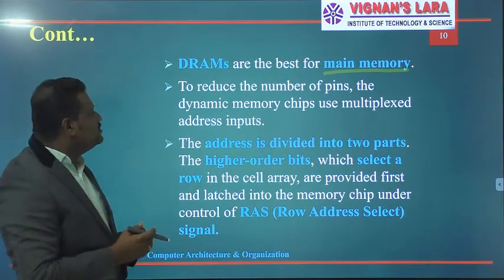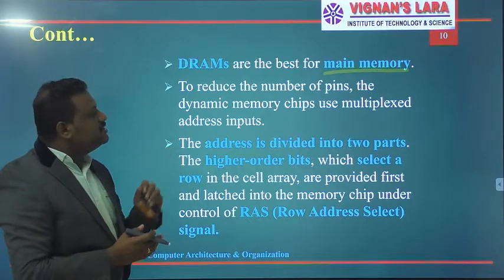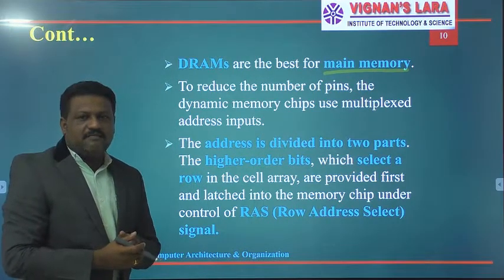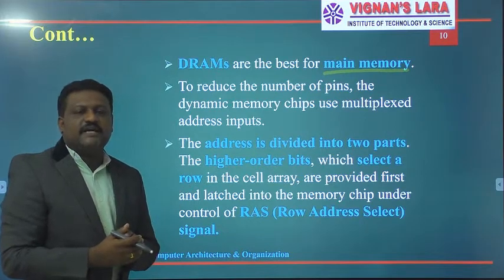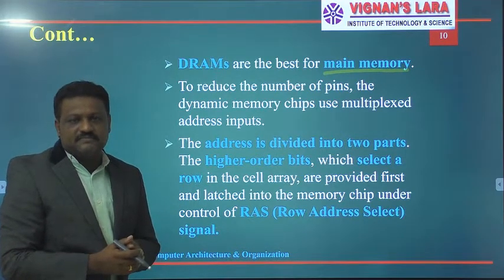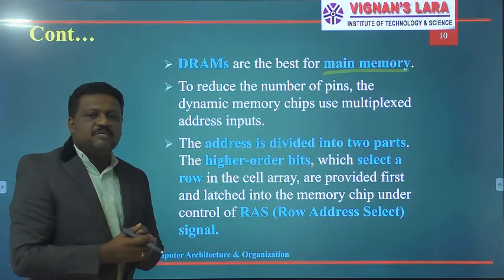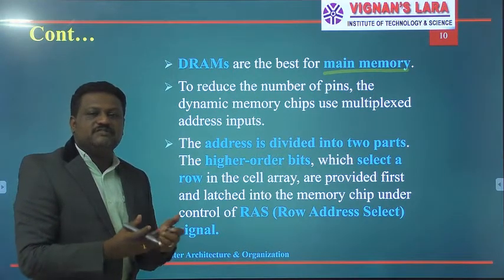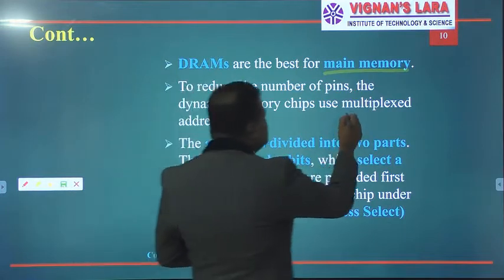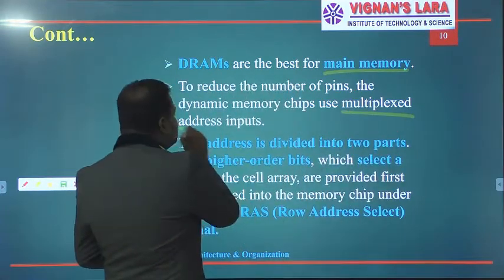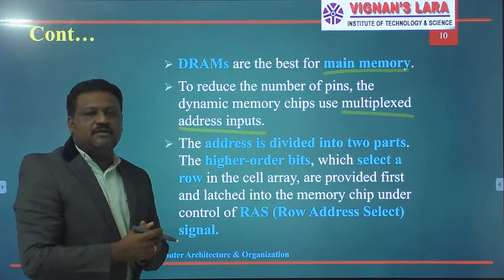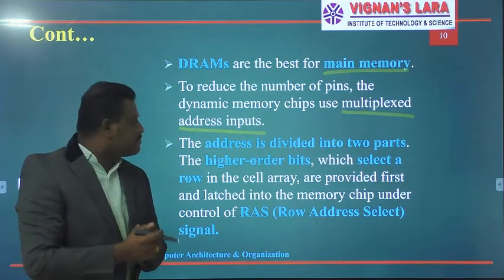To reduce the number of pins, the dynamic memory chips use multiplexed address inputs. We know that each and every location can be identified with some unique address. In the case of dynamic memories, to reduce the number of pins of memory elements, we are going to use a concept called multiplexed address inputs. What this is, we can discuss in upcoming classes.